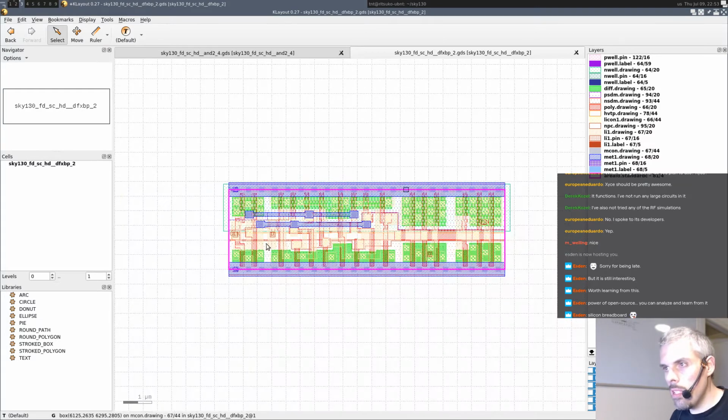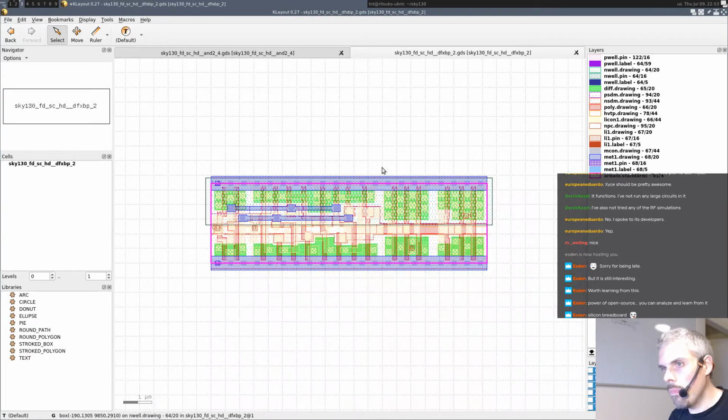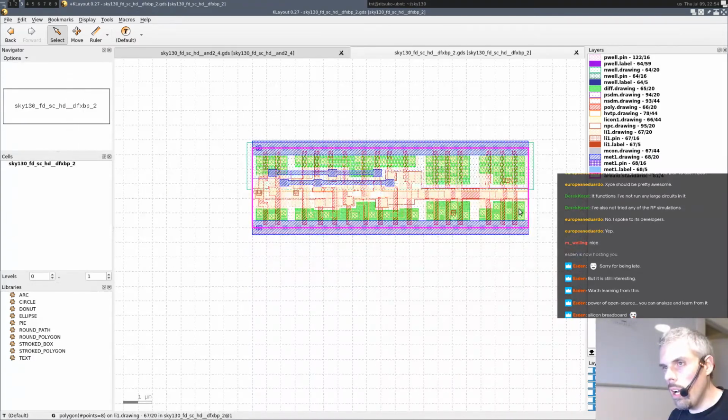There is one limitation that I just learned this afternoon, which is that in all these standard cells, if you look, you will not find any connection to the bulk of the transistor. So I mentioned earlier that the PMOS and NMOS are quad terminal devices. You have a bulk connection.